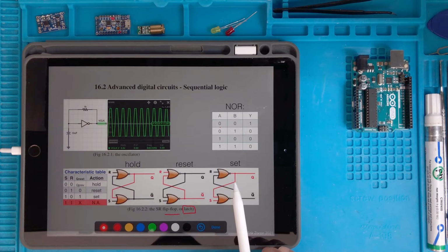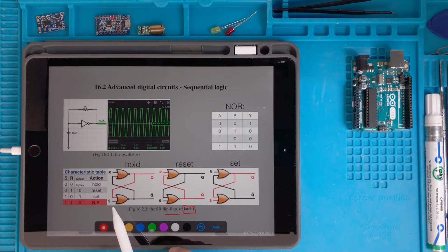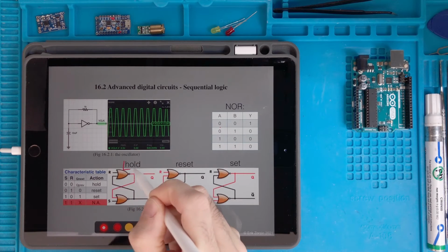Now finally we can start from this, and we go back again to this other condition. So what happens now if, once we reach this situation, we don't touch the reset, but we release the set input? From this condition, Q was at 1, we already analyzed this from the very beginning. Now we produce this situation here with the set condition. So if we are in this situation and we change the set input from 1 to 0, then the Q state at the output remains the same. This situation is called hold.